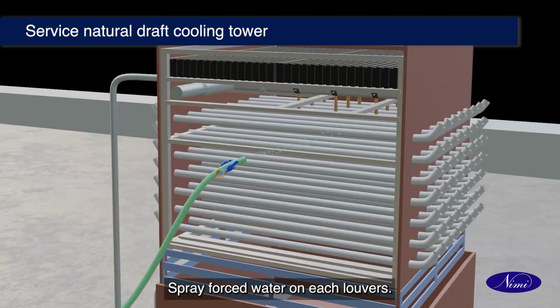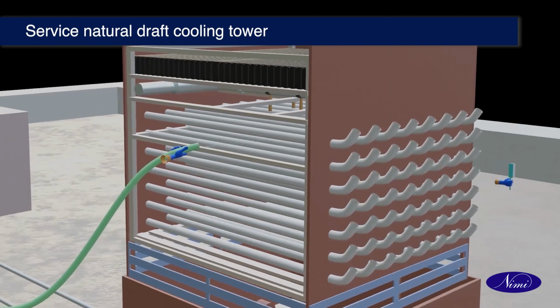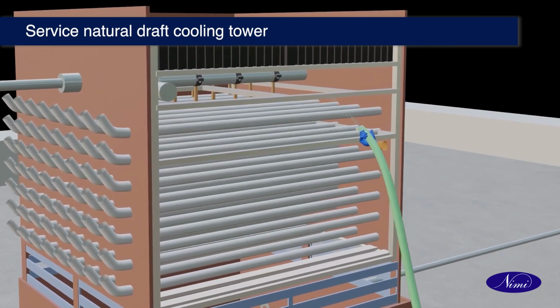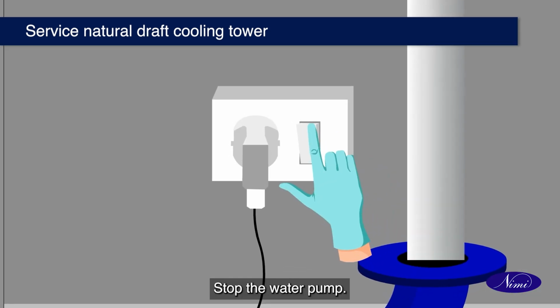Spray forced water on each louvers. Rub with a brush having hard bristles. Again spray with forced water. Repeat the procedure till it gets cleaned. Clean each louvers with cloth. Clean the water tank. Stop the water pump.